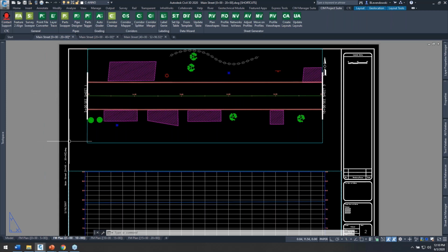So this is one of the real straightforward examples, just taking something like M text, which ends up filling in a lot of the gaps in our sheets where Civil 3D annotation does not cut it, or it's just too kind of specific, right? For one, it only works on Civil 3D objects, except for line and curve labels. And 2, you don't have a ton of control on what data is displayed within that. So let's put some M text on all of these driveway polylines, but we're going to do it all at once. And we're going to read the area of those polylines and insert that into the M text all at once. So again, 3 drawings, multiple layouts, multiple sheets at once.